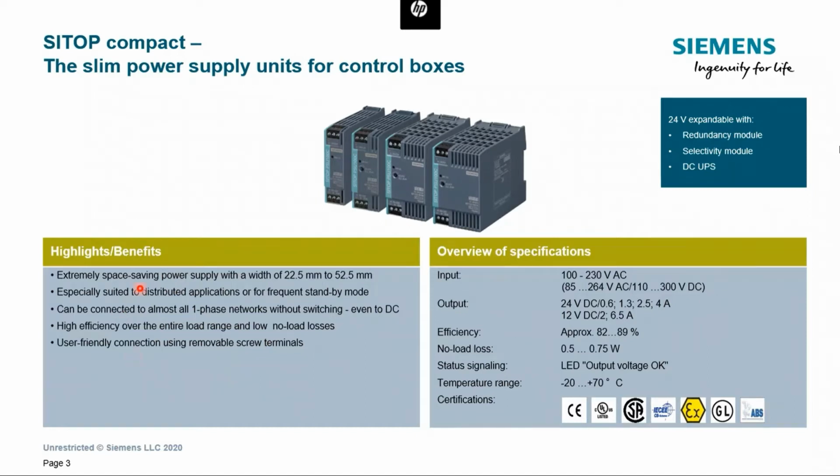The intention behind it was to use it in control boxes and distribution boxes. It is well suited for standby mode applications, where the system has no actual load for a long time, because this power supply has very low losses at no load, as you can see here.